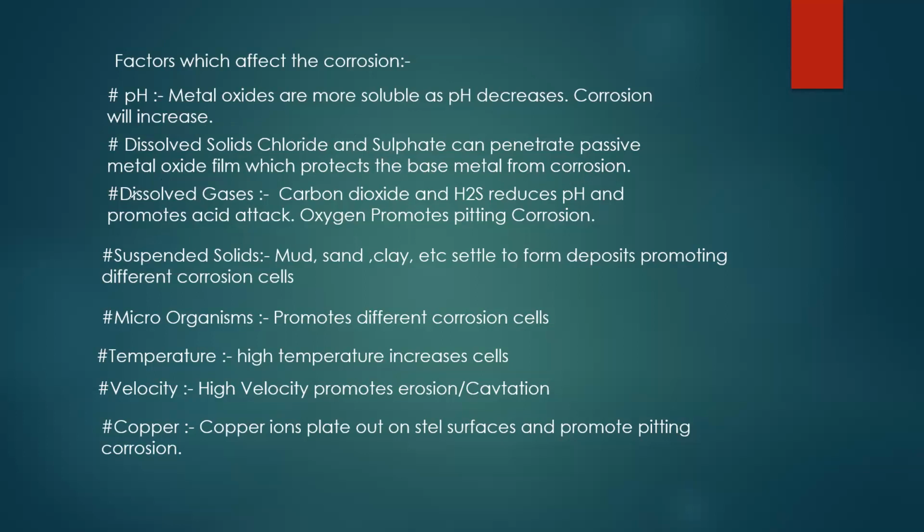If you have dissolved gases like carbon dioxide and H2S, they reduce the pH and promote acid attack. Yes. Oxygen promotes pitting corrosion, right? We already studied this. Oxygen promotes pitting corrosion.